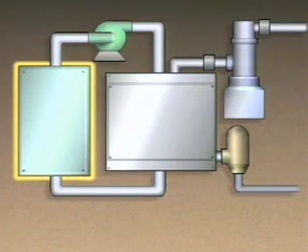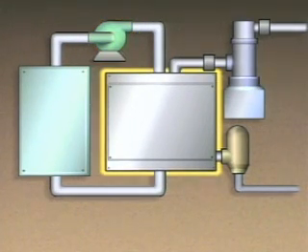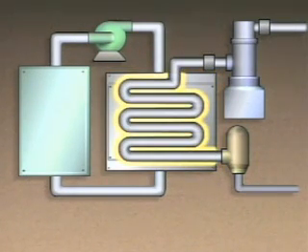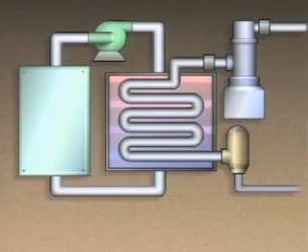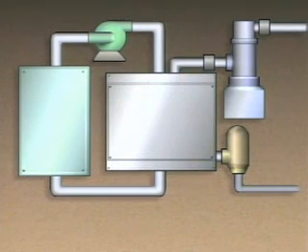The brine flows through the process equipment where it absorbs heat and cools the equipment. A pump is used to create flow through the brine cooling system. The brine is then pumped to a heat exchanger. The heat exchanger in the brine cooling system is the evaporator in the refrigeration system. In the evaporator, the brine acts as the heat source, and its heat is absorbed by the refrigerant. As the refrigerant flows through the evaporator, it changes to a vapor. The refrigerant then flows on through the rest of the refrigeration system. The cooled brine is directed back to the process equipment, and the cycle continues.